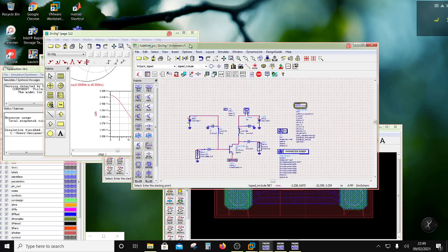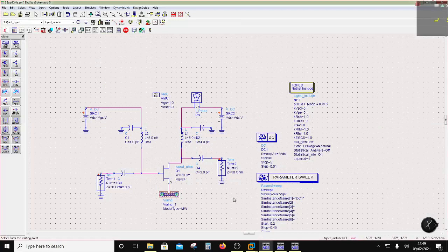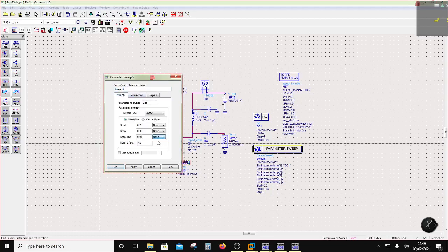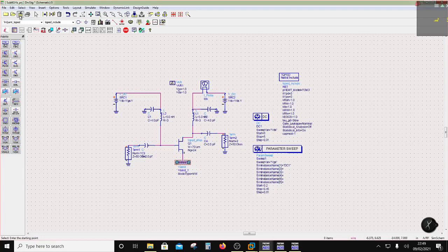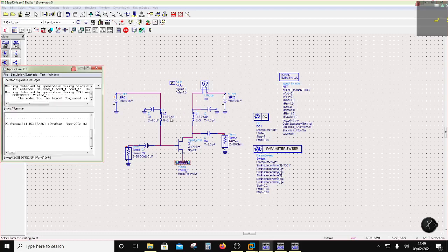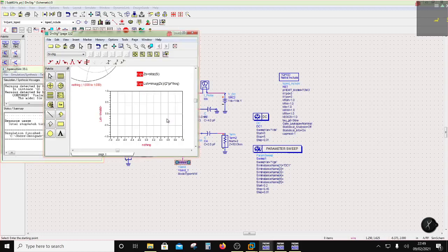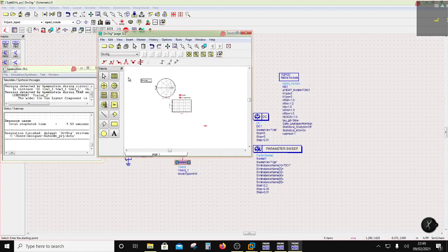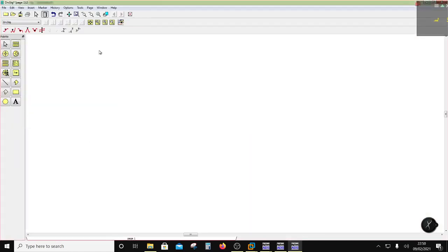Okay, so now that we are done, we are ready for the DC simulation, right? So again, why is it not showing this step here? Because of this. Okay, so now I am going to just do a DC simulation on this, and establish a quiescent current. Later on, I will come and tell you what the differences are. Okay, so don't worry about it. Okay, this is from somewhere. I'm going to just delete this. Oh, this is from the previous one, right? We were finding out the inductance.